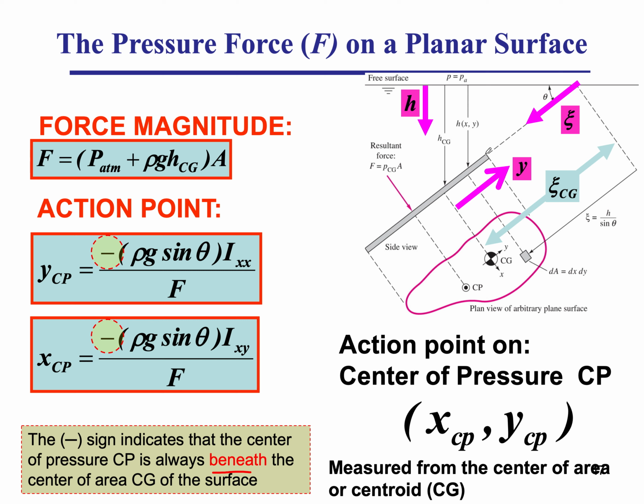And now if I ask you to tell me what this hydrostatic pressure distribution that we started with looks like, well, what is the pressure at this point? It's rho g times h, plus p atmosphere, of course. And this is a higher depth, so it's rho g times a higher h, higher rho gh. So this is the pressure distribution we're talking about, and it's linear.